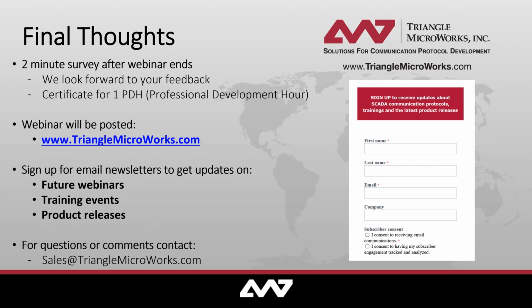I will point out that from a computational perspective, it is more difficult to do on a Windows platform. Depending on the number of sampled values that you need to subscribe to, you could need a more powerful PC. And then of course you do need some way to generate those sampled values, which is even more computationally intense. You can do that in DTM, but we've also seen people use external test sets to generate those sampled values.